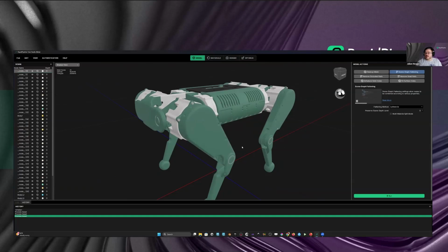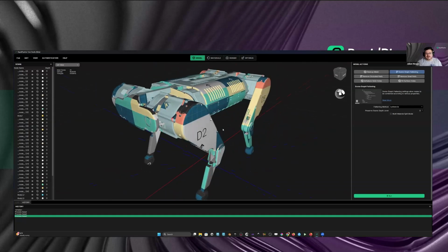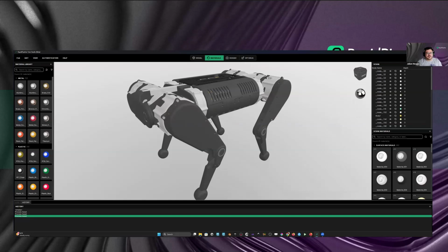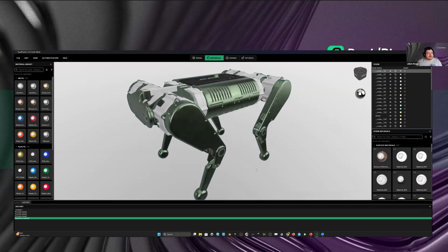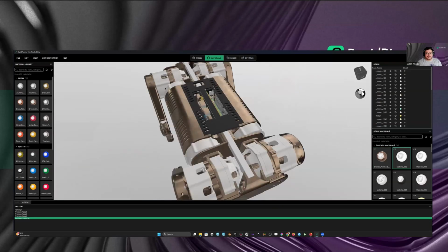And of course, as I said before, we want to make this type of workflow work also without performing the flattening. But this is also a cool feature. Flattening, of course, saves a lot on draw calls as well. And as you can see in the UV view, we managed to do this fairly quickly. If we go in the material tab and do the same thing again, we identify the material, replace it, deselect it, and now we have the cool pattern from our texture already on it.